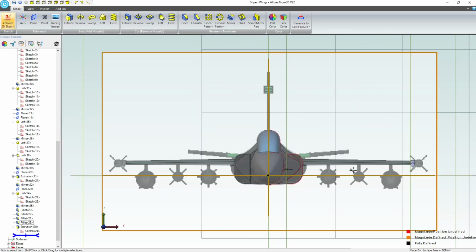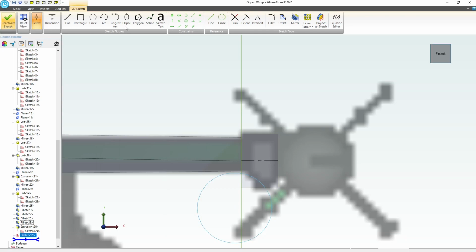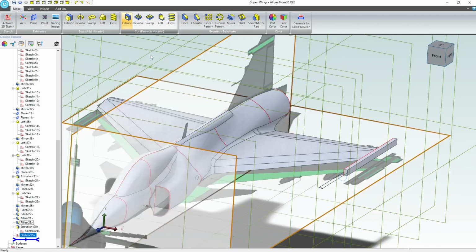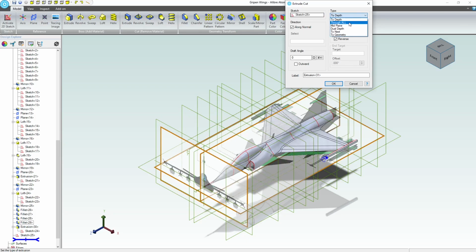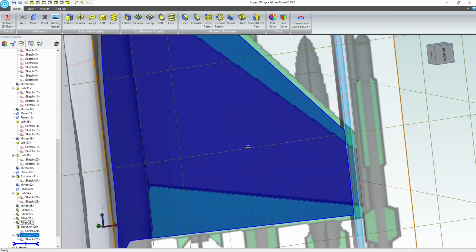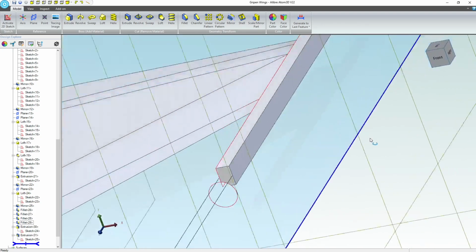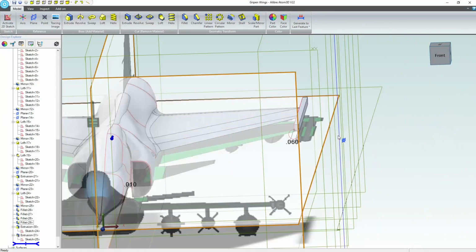I'm going to make a sketch on this axis, and as kind of a cool visual feature, I'm going to make just a circle that's going to cut part of this out. You can see the bottom of the wing, so I'll adjust my circle right about there. With the activate, we'll do a cut extrude, and maybe through all. I don't see a problem with that. So if I look under my wing, yep, that's how I wanted it. And we can add fillets on that later.